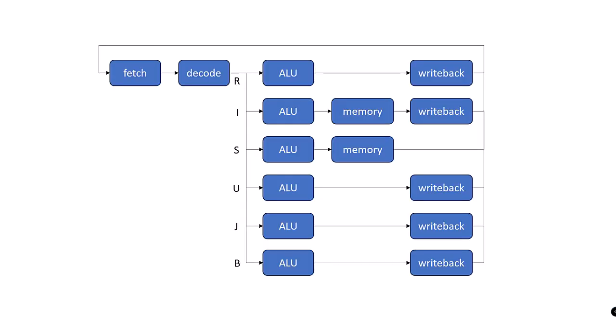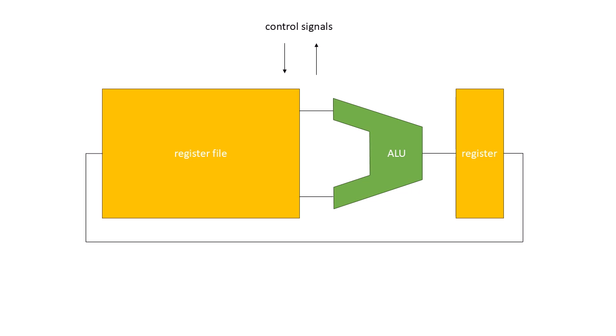We're now ready to create a controller that executes all of these instruction types. The fetch and decode operations are shared. The succeeding stages depend on the results of the instruction decode. Not all instruction types use all of the stages. The shared data path can be built by adding multiplexers for selecting sources and registers to separate stages of execution.